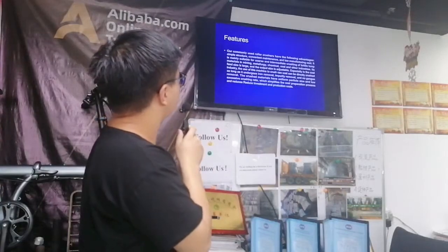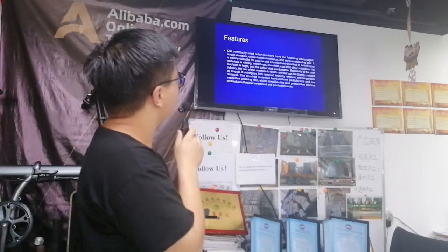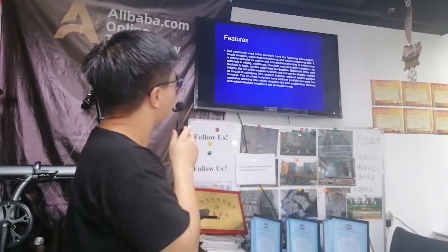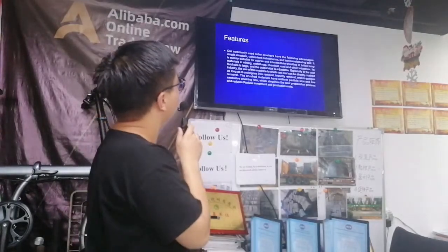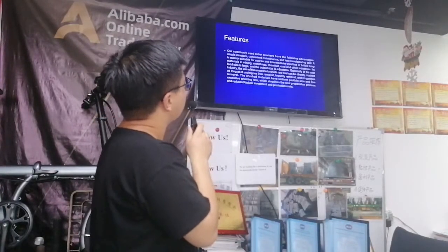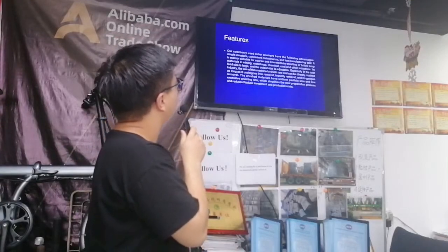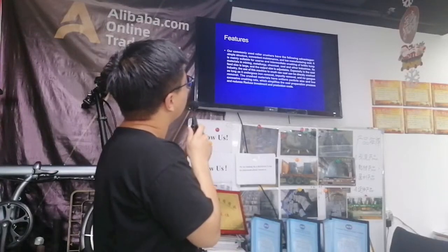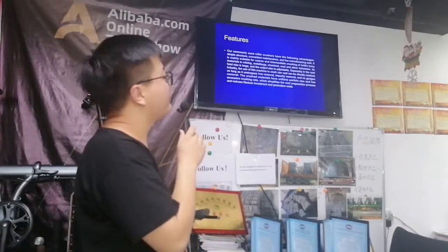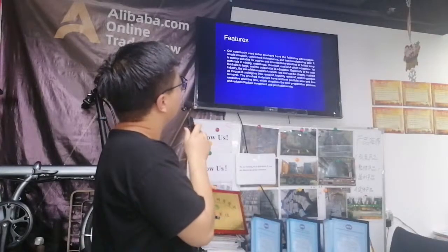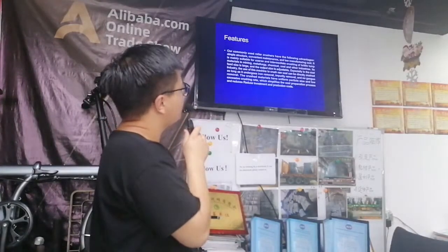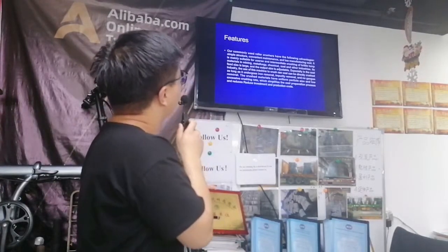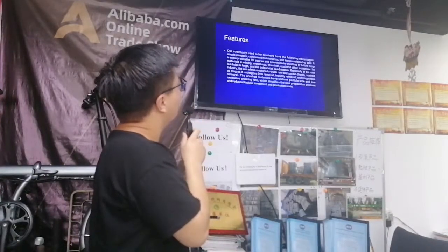The features of roll crushers have the following advantages: simple structure, convenient maintenance, and low cost. It is mainly suitable for coarse and intermediate crushing of brittle materials in the chemical, coal and other industries. The feed size is large, and the output size is adjustable.